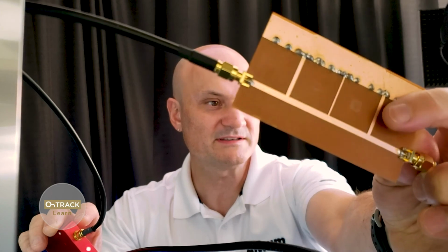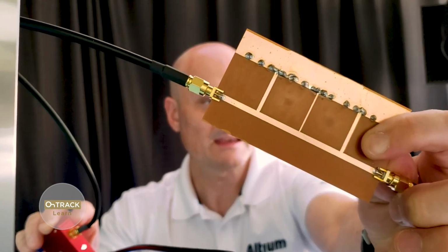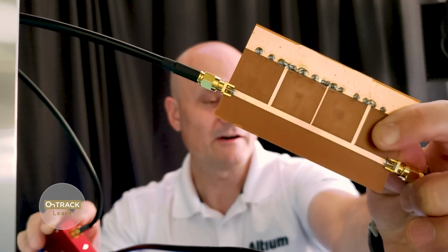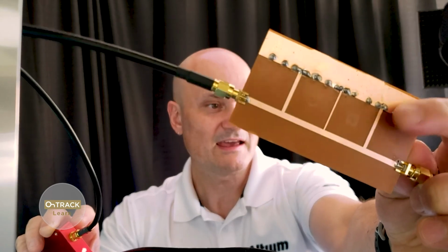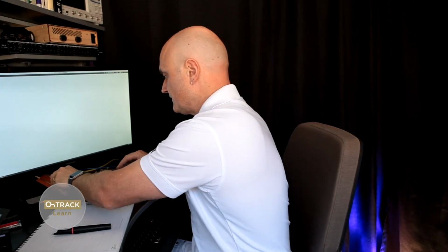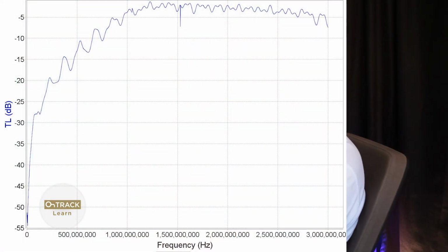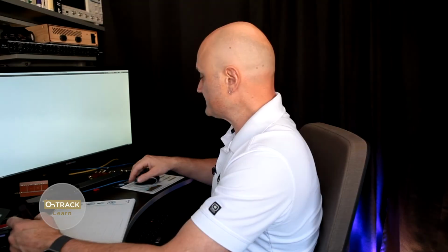At the center frequency, where these are a quarter wavelength long, these are open and passing, and at higher frequencies these become more inductive again and cause a roll-off in the high frequency response. And of course, I can just put up a screenshot here. This is the actual measured frequency response from the VNA of this particular filter. And so filters can be built up of those kinds of elements.